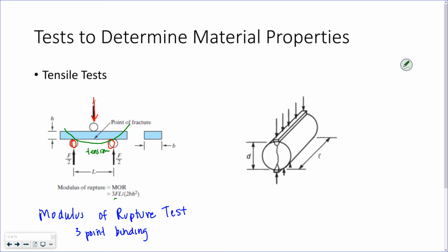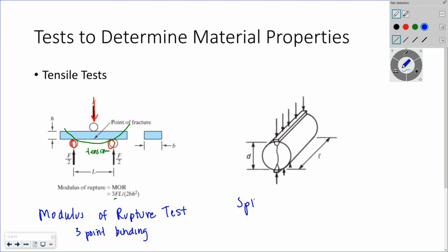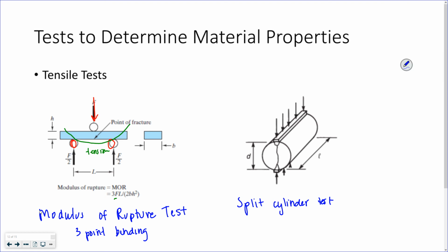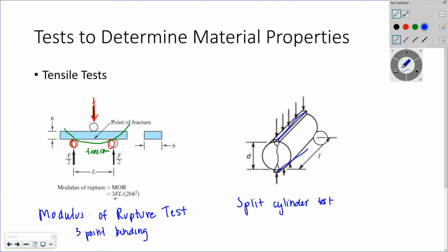Might also do the split cylinder test. That's the one on the right. Where you're supported along the length and you apply a load on the top.